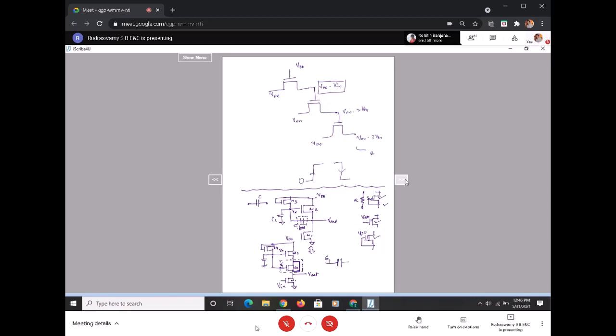So this gate is a metal. Then I have an oxide. Then this is a semiconductor, which is basically highly doped. Again, it is a metal. It is now a two terminal device: gate terminal, source and drain shorted. So now, is this equivalent to a capacitance or not? Yes or no? Yes, that's it.